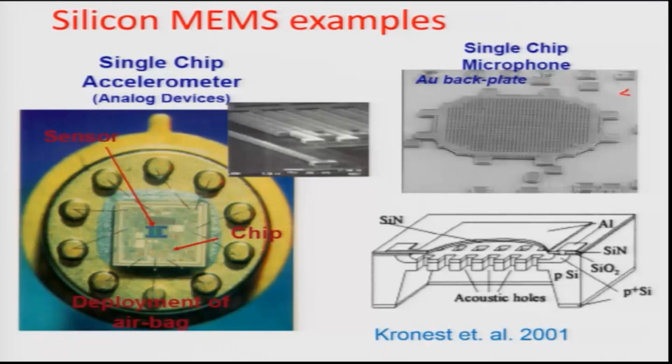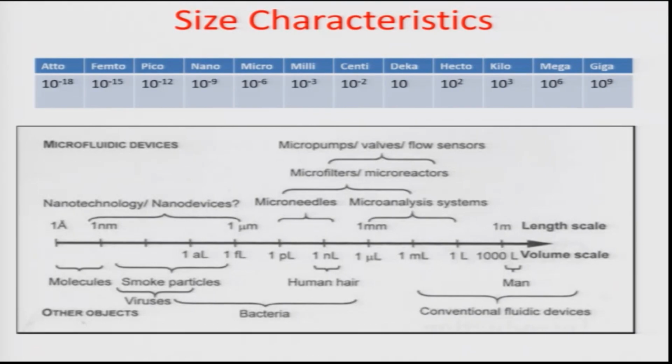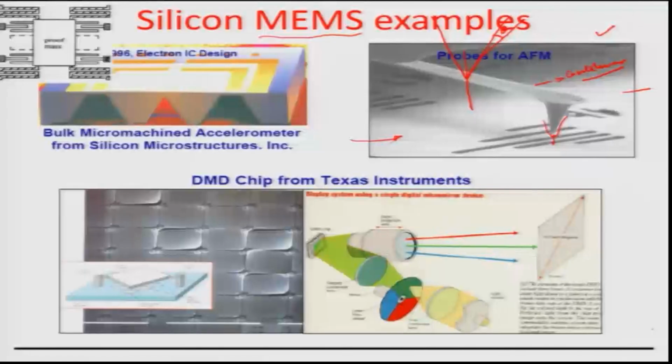So, that is what AFM, or atomic force microscope, is. It is again a device which comes under the realm of the micro electromechanical systems. Think of it as a change in an optical signal because of a bending process which happens right here at this small cantilever tip. So, a mechanical signal is converted into an optical signal, and then because of that optical signal, an algorithm computes the exact topology over which such a tip scans, which is what is directly visible out of the probe of such an AFM.